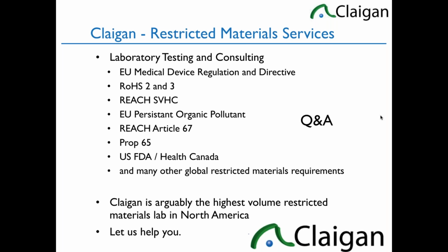As I mentioned earlier, the overlap between the MDR substances and RoHS and REACH SVHC is very heavy. REACH SVHC is a few extra persistent organic pollutants, respiratory sensitizers, which are under scope of some part of the MDR, but there's a lot of materials in common. The thresholds are different, human contacting, invasive versus anywhere in the product, but a lot of the processes are similar. So as long as you modify your process properly, you should be able to handle more than one at one time.